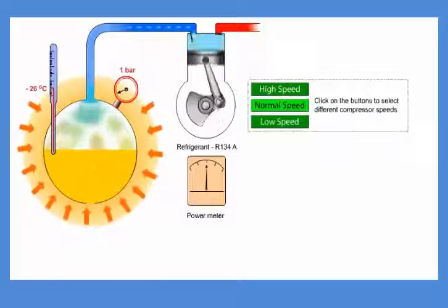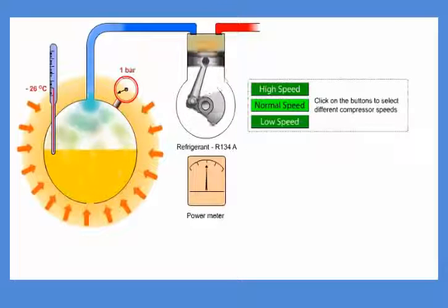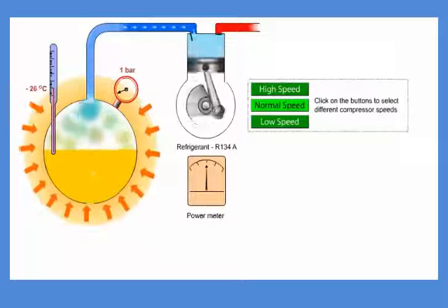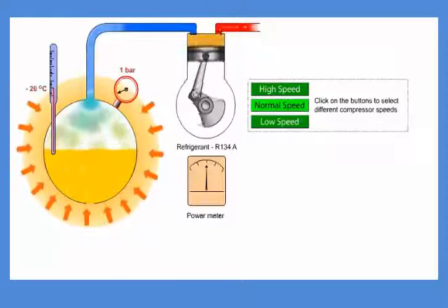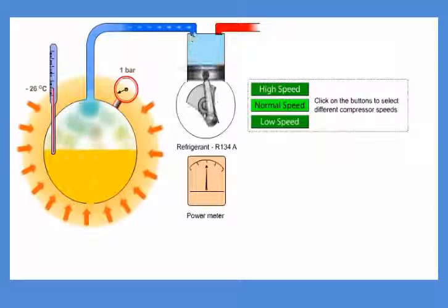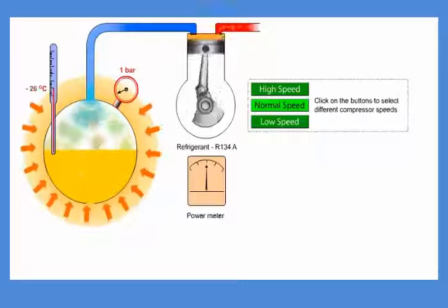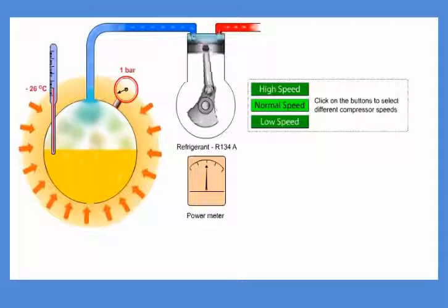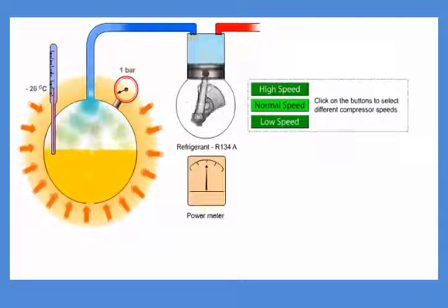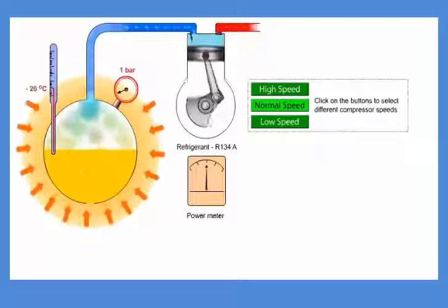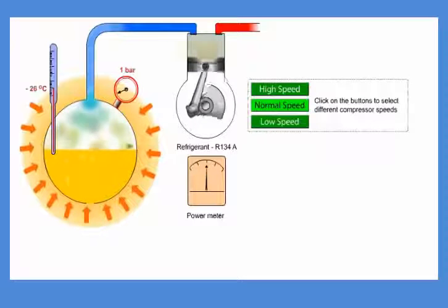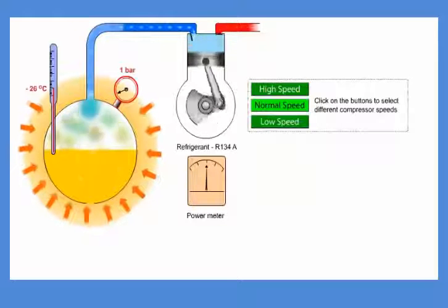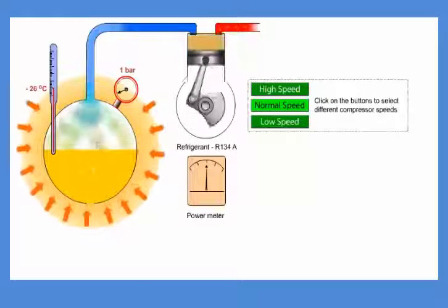There is coherence between pressure and temperature in the compressor, which leads to a higher temperature on the outlet of the compressor. The temperature on the compressor outlet measures plus 36 degrees Celsius in this case. In order to be able to compress the vapor, the compressor needs a supply of mechanical energy. In this case, an electric motor is driving the compressor.